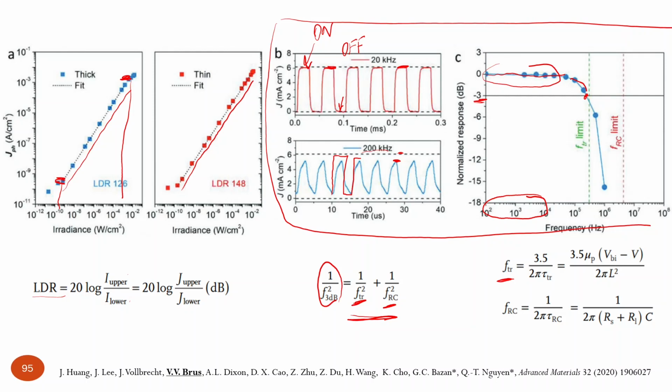So obviously there is some distance, there is some drift speed, and it takes time to move from one edge of the active layer to another. So that will be a function of the mobility of charge carriers, of the electric bias which is applied to the photodiode, which together with the thickness L defines the strength of the internal electric field.